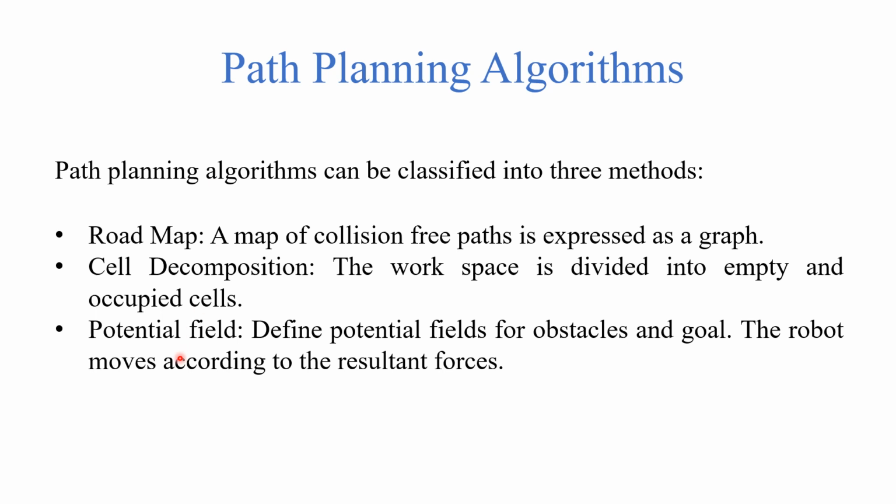Now, the type of algorithms that we're actually interested in for this project is the potential field algorithms. In this case, we define potential fields associated with goals and potential fields associated with obstacles. The ones associated with the goal are attractive. The ones associated with obstacles are repulsive, and the robot moves under the influence of the total force, which is the sum of all of these forces. This should guide the robot, in ideal cases, towards the goal while pushing it away from the obstacles.